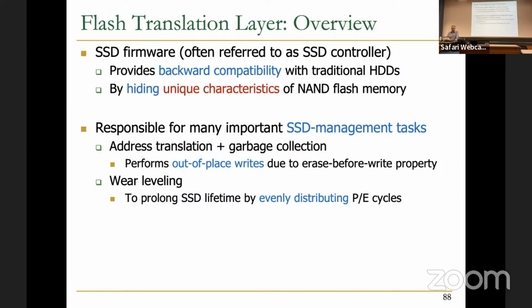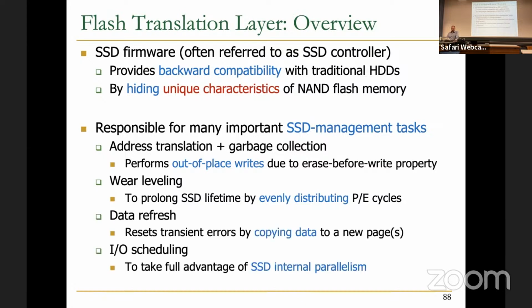We're going to discuss address translation plus garbage collection, which is essential for performing out-of-place writes. It also does wear leveling, data refreshing, and I/O scheduling. Today, we're going to see address translation and hopefully I/O scheduling. Wear leveling we're not going to cover, and data refresh we're going to cover a little bit tomorrow, hopefully.